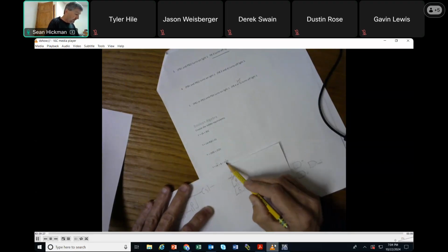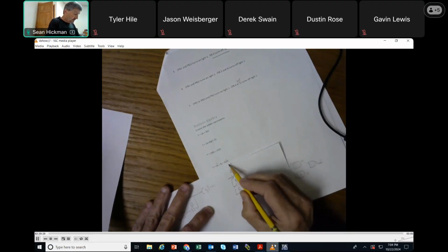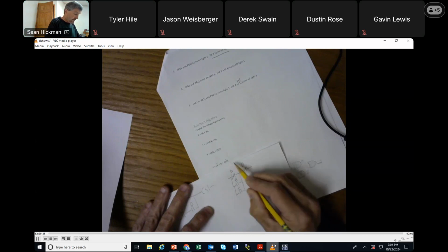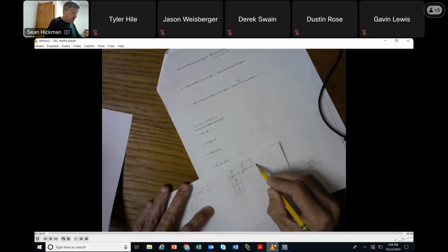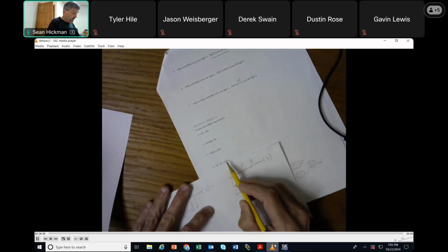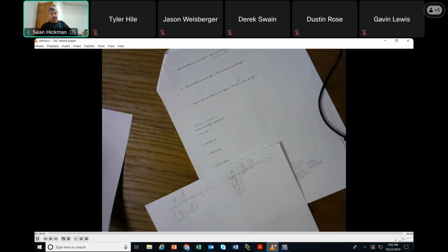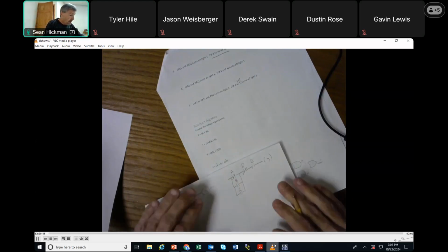Not A, B, C. And not D, E equals Y. So the ones with the lines over them, they just become normally closed contacts when you go into ladder logic. Okay, that's what I'm coming up with for that one.